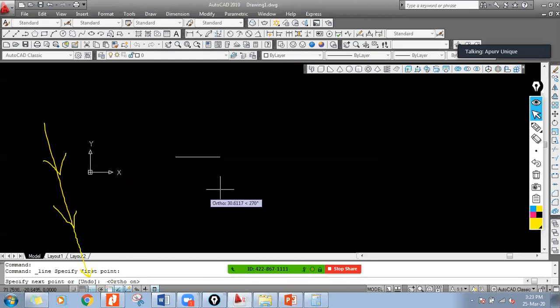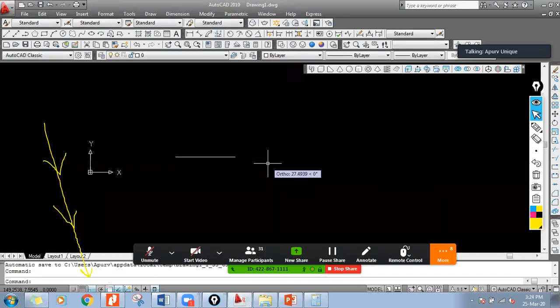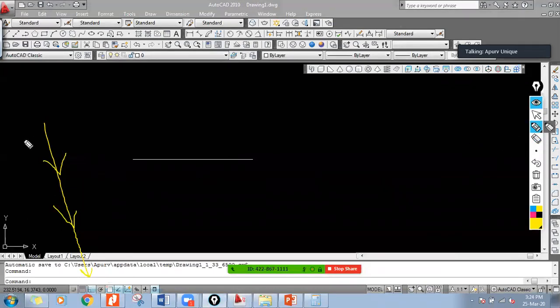Right now, you just check. This is your drafter is on. Your set square is with you right now. You can draw either a vertical line or a horizontal line. Clear? Yes, sir. Now, suppose I just write 50 mm. I just write 50 as my input. This is the 50, and I make enter again. Right. So I am able to draw a line whose length is 50 mm. Correct.